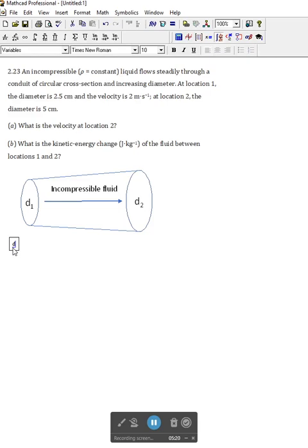And so I'm just going to say D1. Now I can have D1 as all the same case, but I like to use subscripts where it is convenient. So to do D sub 1 in MathCad, to get a subscript, you type period. So D period, and you see the cursor moves down 1. So that gives me my variable D1.